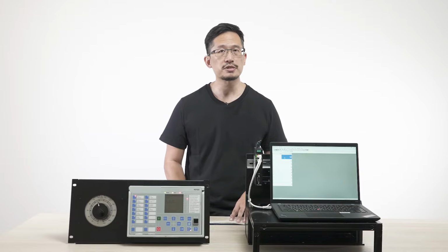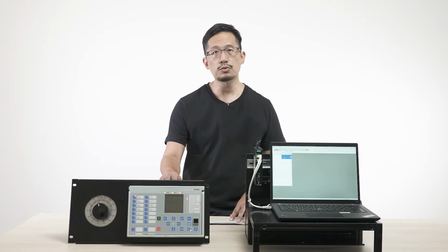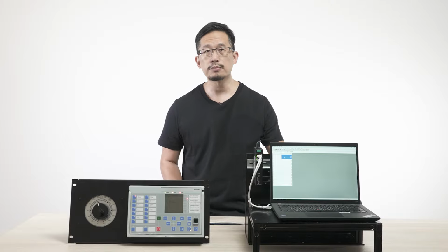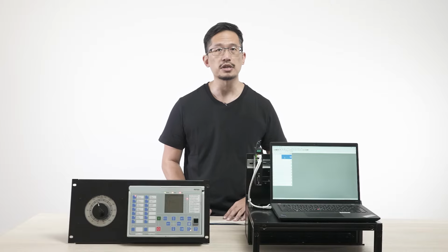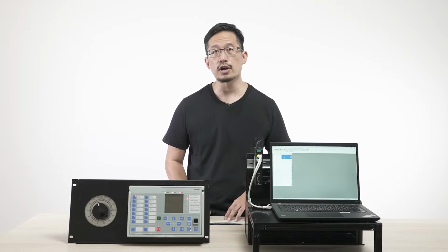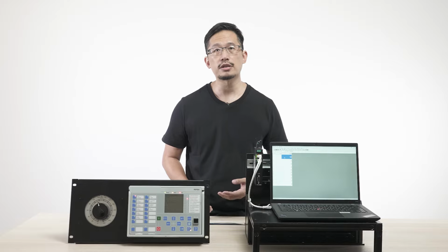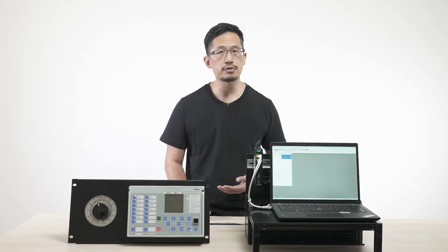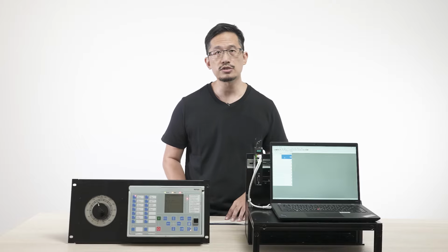Today, I'm going to demonstrate how you can monitor an IEC 61850 IED with a Modbus TCP SCADA and perform basic communications. For this demo, we're going to monitor the operating frequency of our IED, and that can be used to monitor the operating frequency of an entire power system. Now, the operating frequency is important because it determines the parameters of a lot of components in the system, such as generators, transformers, and other electrical equipment. If a frequency drop is detected, then the IED needs to trigger protective actions to prevent a power outage.